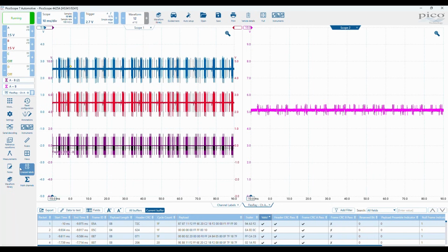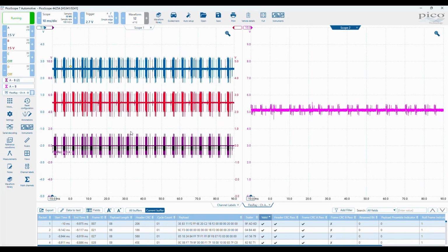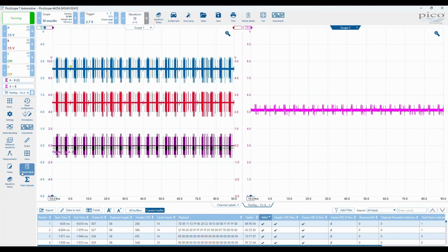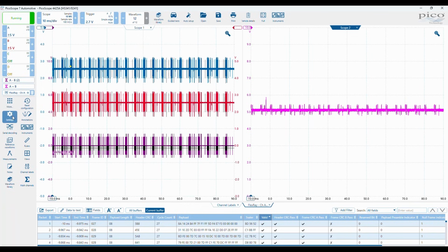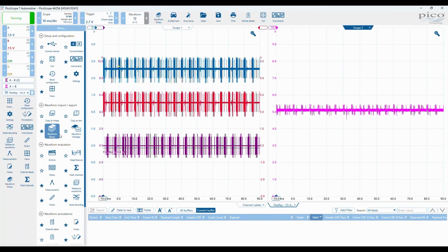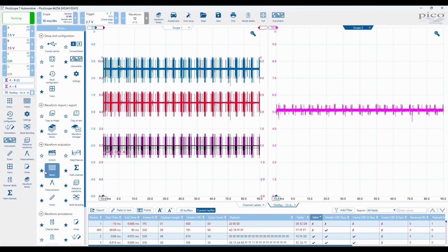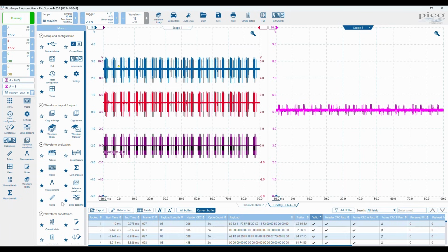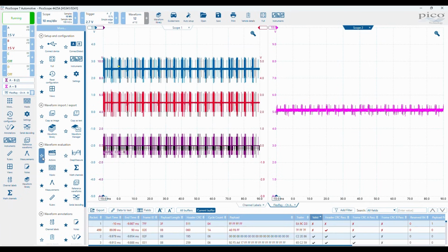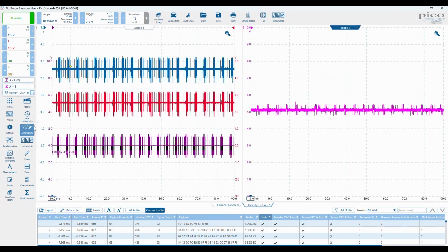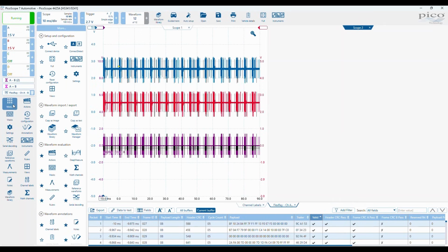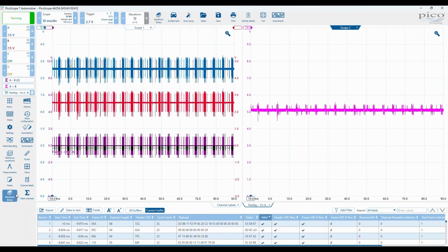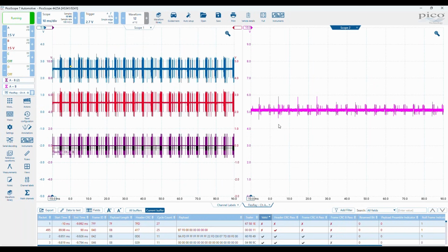So we want to add something called a mask onto scope view 2. So we go to masks, which looks to be under our more panel. There it is. If I click on the bold star, that star there, we now move the masks so it's always available here. So it becomes a favorite. That's it. So we're customizing the scope, and we also want an action as well. So now they're here without having to click on the more button. Now, what does a mask do? Well, we'll put a mask around this waveform here, this A plus B.